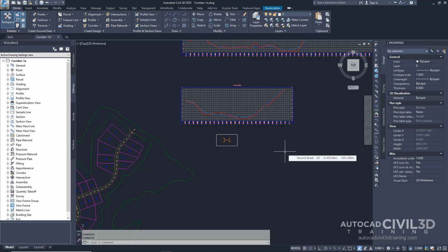A corridor model builds on and uses various Autodesk Civil 3D objects and data, including subassemblies, assemblies, alignments, feature lines, surfaces, and profiles. Corridor objects are created along one or more horizontal baselines by placing a 2D section or assembly at incremental locations and creating matching slopes that reach a surface model at each incremental location.